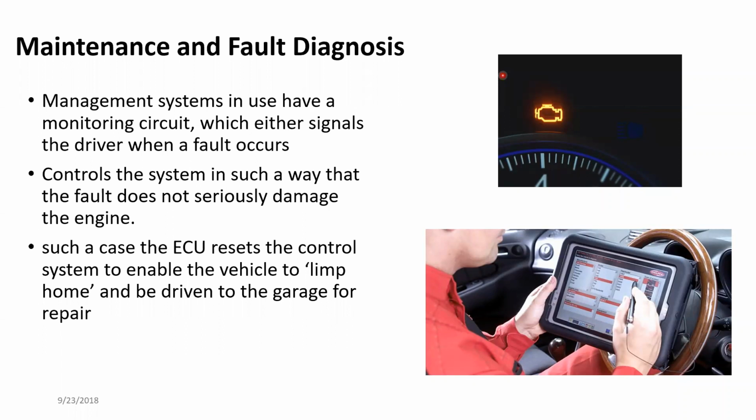Once the engine finds any sort of issue, if the vehicle is still operational, some sensors and modules, without them operating well, the engine can't perform at all. But there are some things the engine can operate without. In such a case, like a small module, the engine will be able to run. For example, if it is the throttle position sensor, the engine can't run, because it doesn't know how much load is requested by the driver.